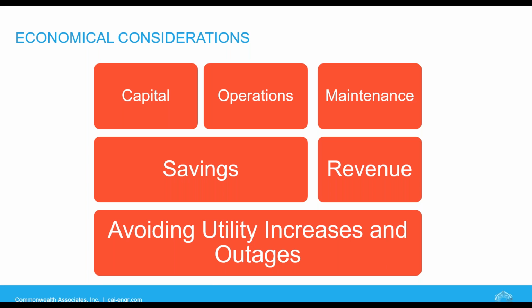Obviously with universities, they have summertime where the kids aren't in school, so the demands of what I'll call the power plant with a CHP would be lower, right? So maybe scheduling that outage during that time makes the most sense, where you're not needing hot water as much, you're not needing as much power. So knowing that service schedule would be vital in helping determine which equipment makes sense.